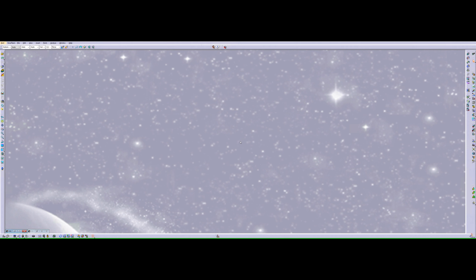This is Kostas, and today I'm going to show you how to create a helix design in CATIA V5. So I will start quickly by creating a new file. In order to create a new file, I have to go to File, New, and down here on the bottom right of your screen you will see that I have to choose part, or the other quick solution is to go there and just type part and press OK.